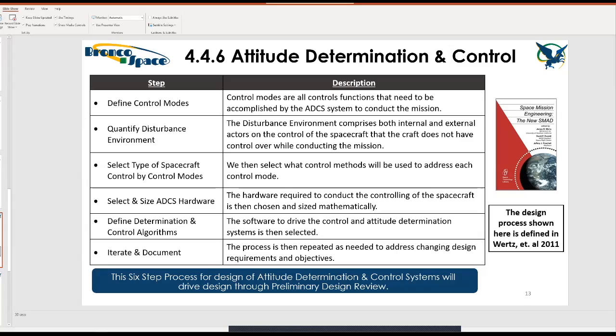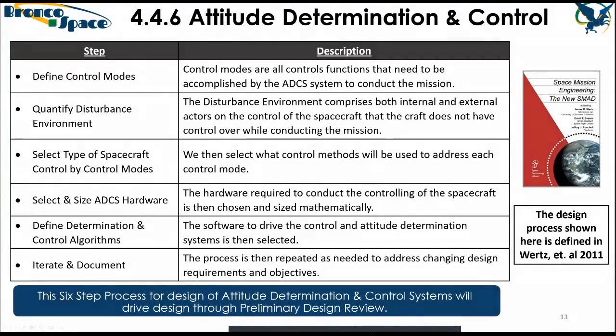Yeah, one of our main problems that we're working on right now, you talked a little bit about it earlier: if solar panels are a big part of your design, you might want to figure out a way to point towards the sun all the time. So attitude control is something we're determining whether we want, a more active system, or just doing the permanent magnet that comes with the fast bus, or getting an actual magnet torquer. And I guess I would like to hear your guys' thoughts on if it'd be worth it.